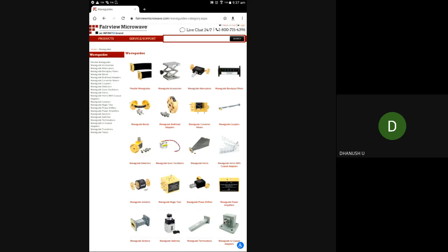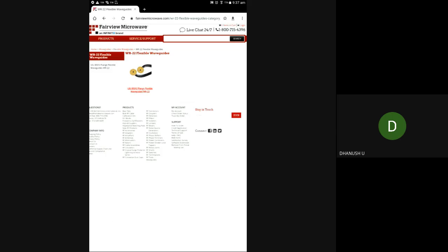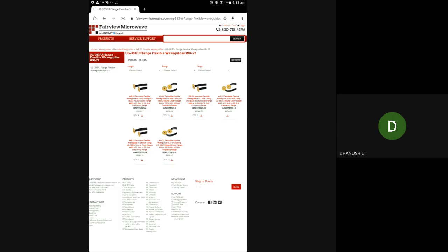You can see these in the lab, which we are using, and we have planar antennas and patch antennas also available. Each waveguide is numbered differently: WR22, WR28, WR34. What is that basically? When you see this, the lower the number, the higher the frequency. I showed WR90; now go to WR22. You can see the frequency is typically 32 to 50 GHz.